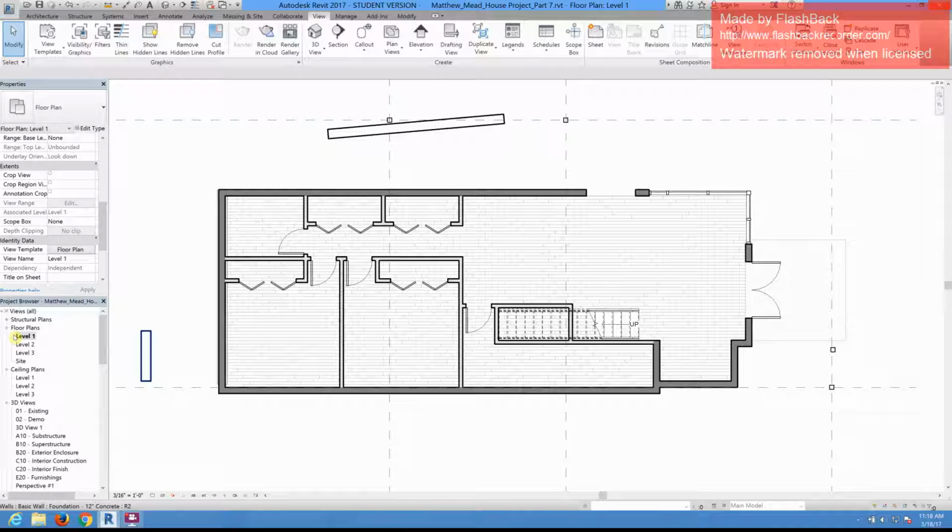At the end of a project, you might have a floor plan template, an elevation template, a section template. You would technically have a template for every view type that you create, okay? We won't get that far in this class because we're not going to create detailed views and draw a lot of the things you might draw if you're doing construction documents, but hopefully it makes a little more sense why you would use a view template versus simply overriding the graphics on every single view. It's an efficiency thing, all right? Any questions on view templates?